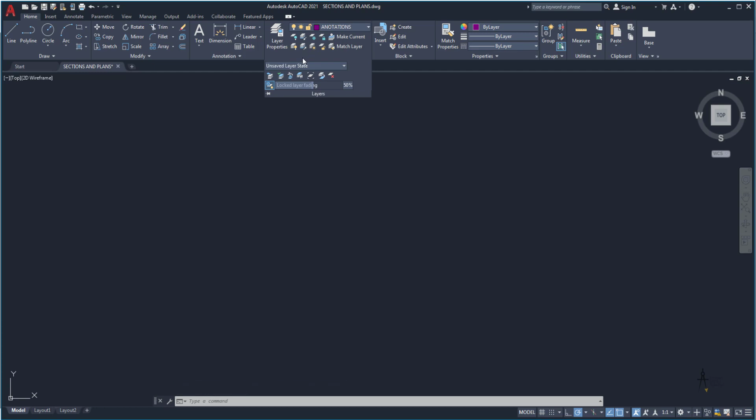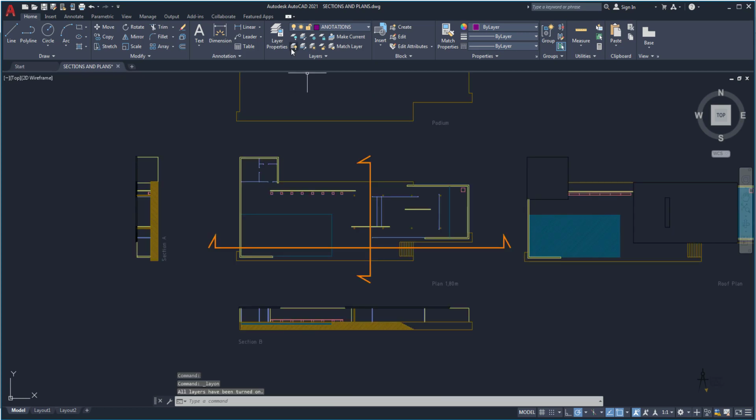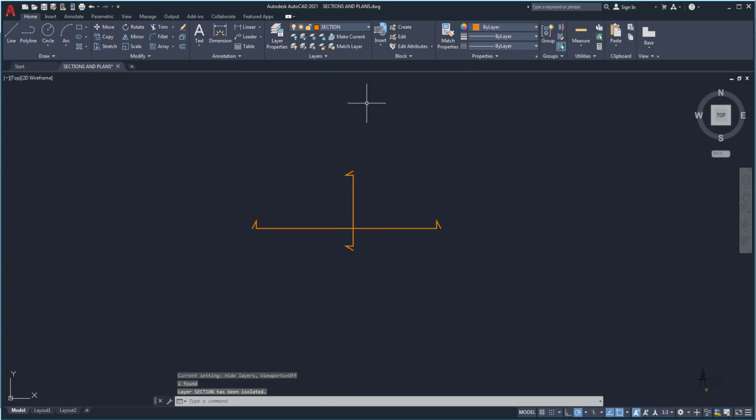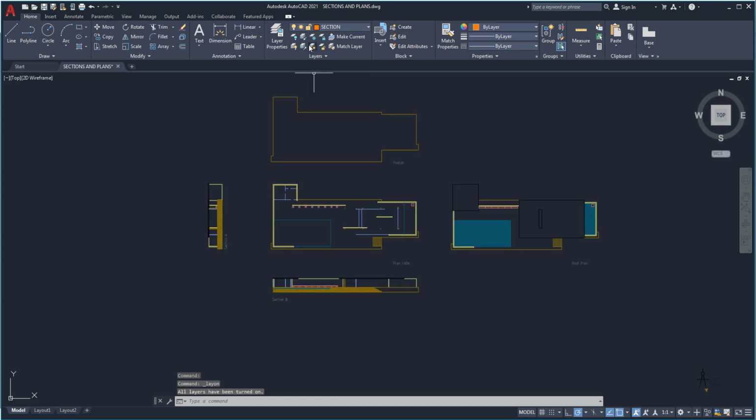You can't just hide your layer, okay? If you hide the layer, SketchUp will identify the lines in the layer, so you actually have to erase the lines that you don't want, okay? Then you've got these lines that tell us where the section is.